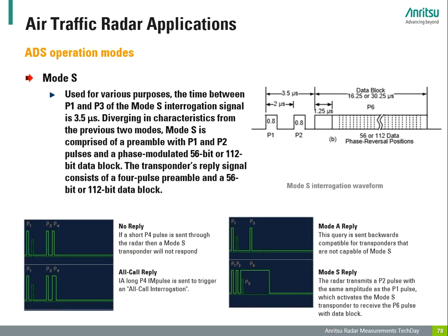You might remember the plot from Flightradar24 that we presented in the previous slide. The results on those maps are based on so-called Mode S transponder information. Such a signal is received on 1090 MHz, and this is the signal pattern that we are seeing here on the slide.